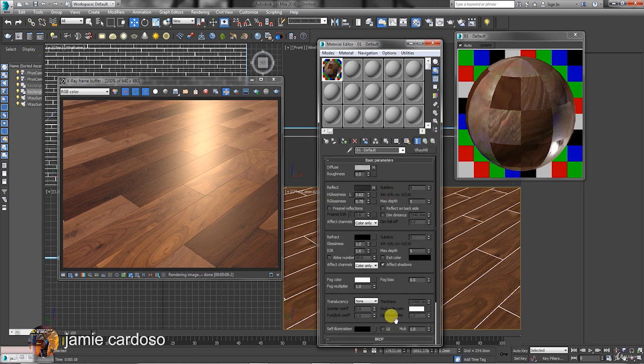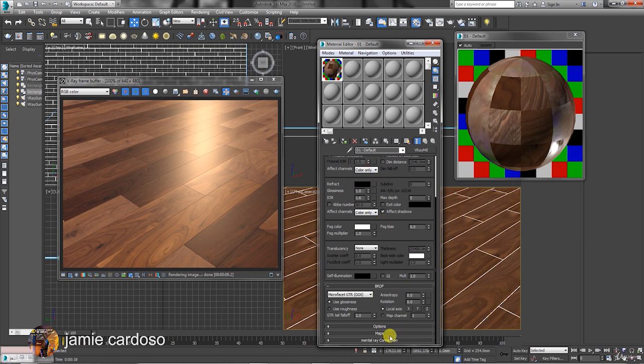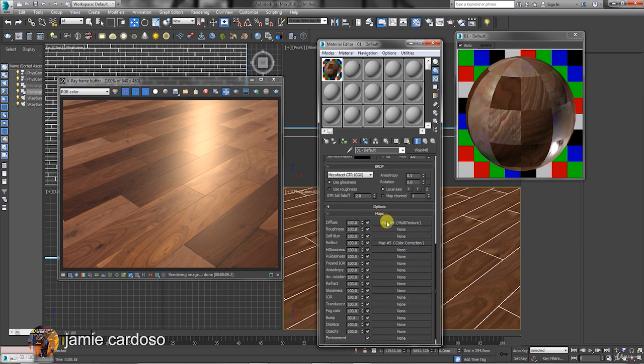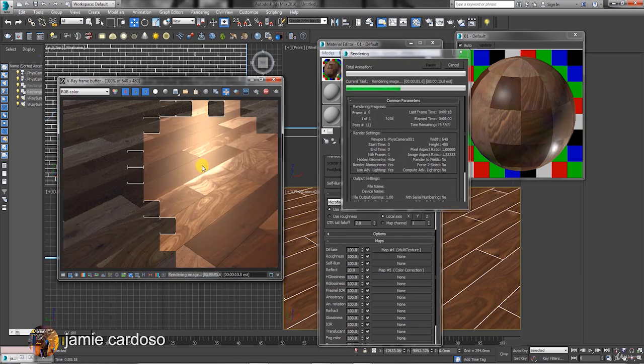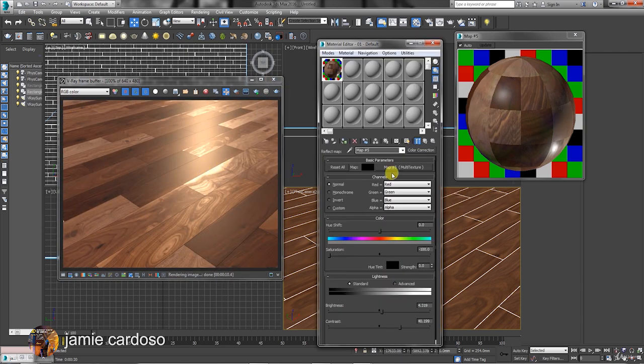Next, we go into the Maps rollout parameters to control the grayscale bitmap. At the moment, V-Ray is using 100% of the grayscale texture to reflect the surroundings. To mix between the reflection color values and the new grayscale bitmap, we're going to reduce the reflect values. Let's do another quick test render. We can make a few more tweaks here and there.